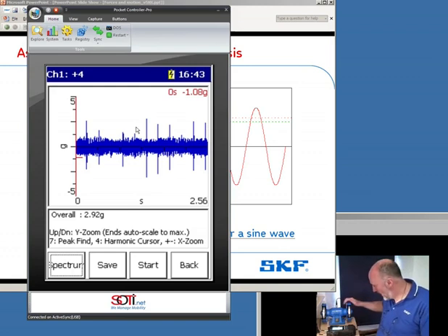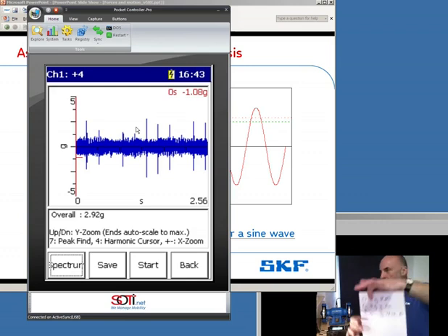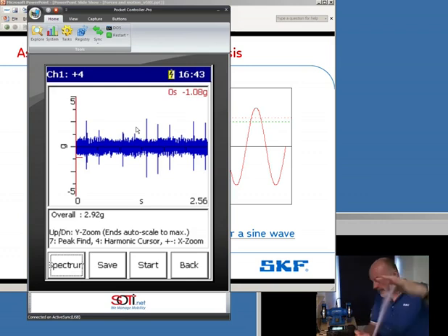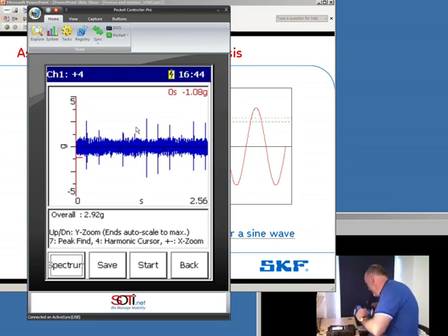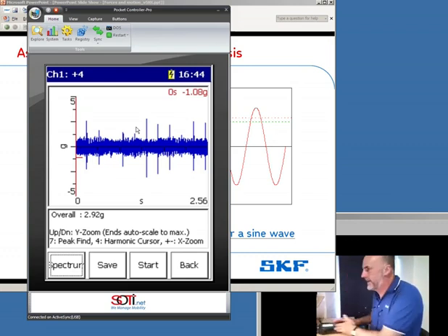So when you're dealing with machinery and you're taking simple readings of machinery health, be careful that those readings only work for simple faults such as unbalance, misalignment, mechanical looseness. You have to have your wits about you when you're wanting to check the health of bearings or gears. And you would need to take a separate type of measurement to do that.